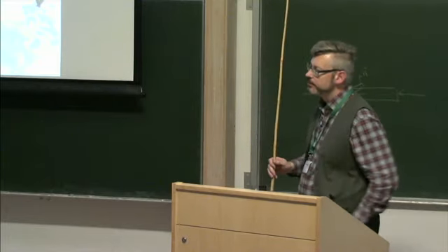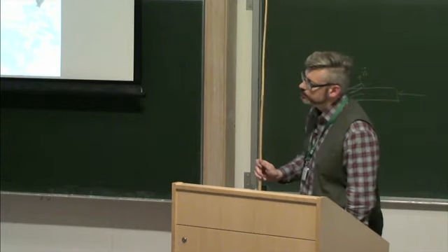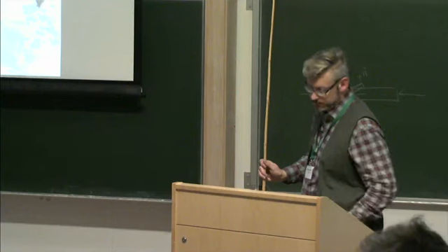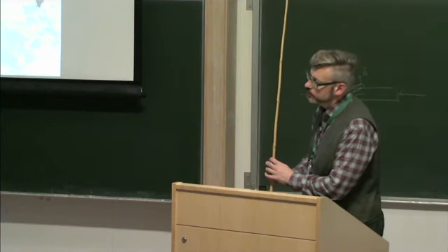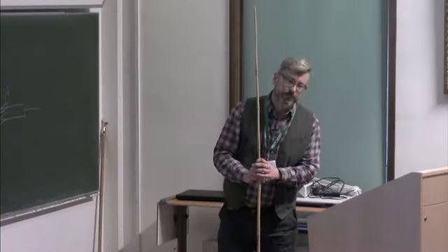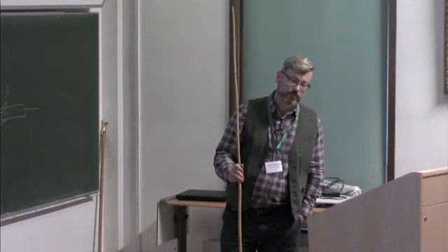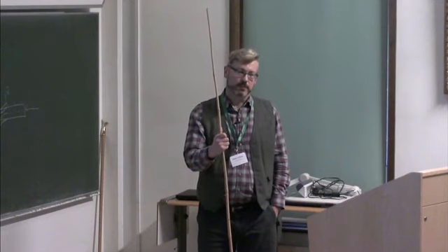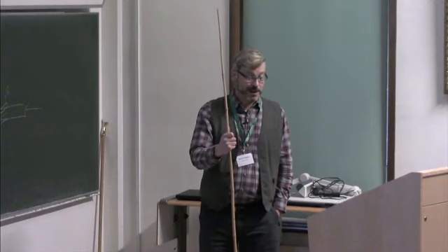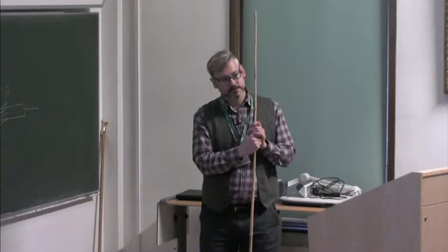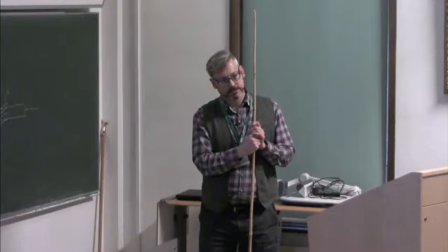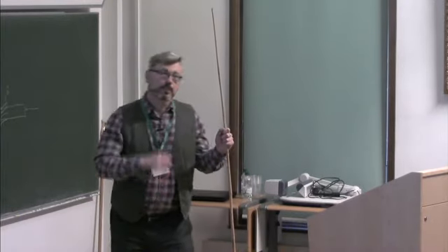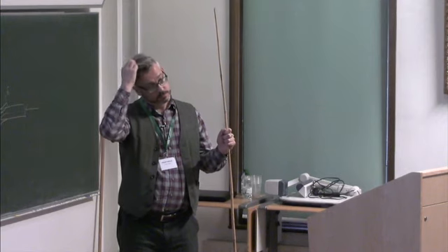Danny, do I understand correctly then that, going back to your diamond-shaped features that are moving collectively, the angle of the apex is set by the coefficient of friction? That's right. That coefficient does vary with the velocity of sliding and a bit with temperature, and we do not account for that. So the question is, how sensitive is your analysis to slight variations in that coefficient from 0.6? Take it from, say, 0.8 down to 0.3.